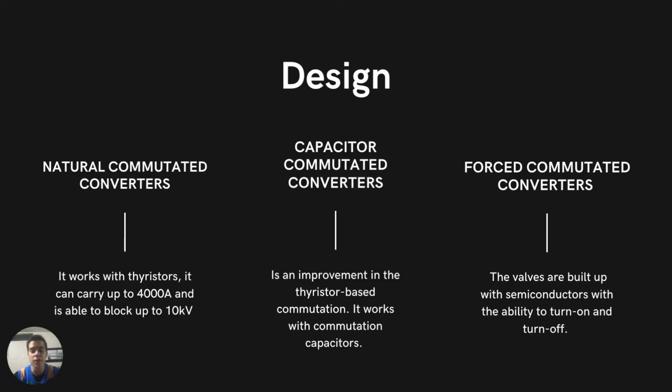Also, by connecting the thyristors in series, it is possible to build a valve which can block higher amounts of volts, and by means of the control angle that the thyristor has, it's possible to change the DC voltage level.